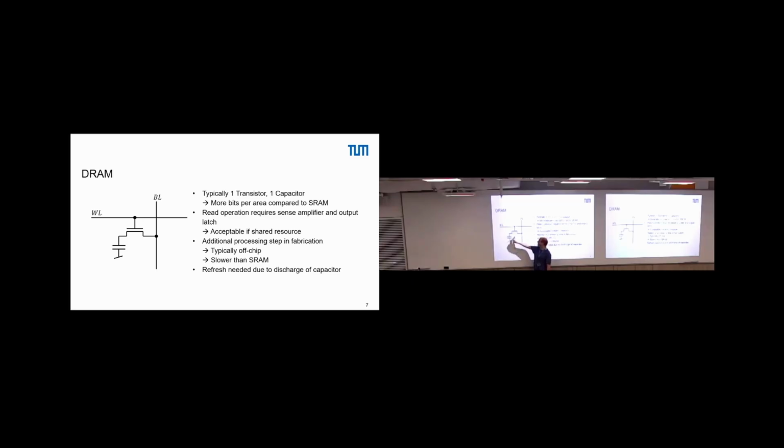Yeah? Then our write process is ended. We can remove the switch and we still store the same value. Okay? In that way, we ensure that the reading process does not destroy the stored value. Somewhat reasonable. So, if we close the switch, the positive charges here recombine with the electrons from here, causing a voltage fluctuation, causing a decrease of the voltage here.